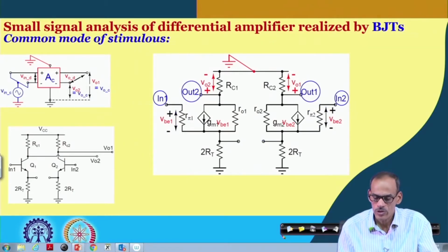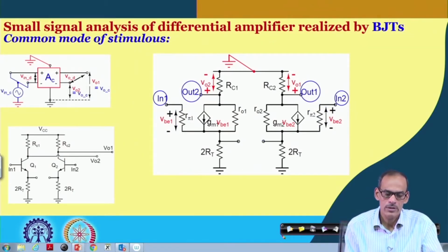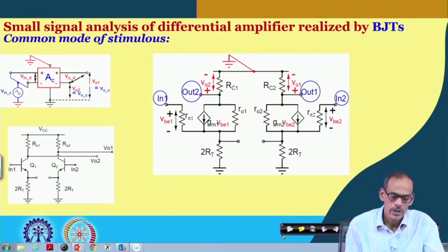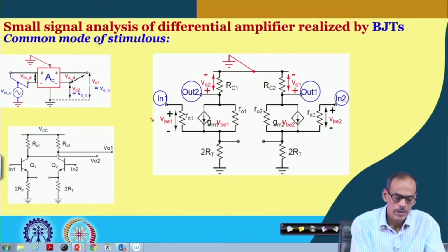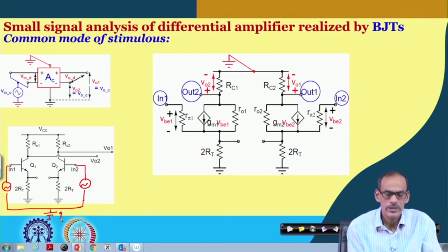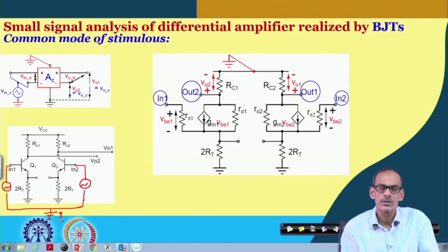Now, so far we are talking about the small signal situation. Now, you may recall that while we are applying the signal at the input, definitely we are also applying a meaningful DC. So, now next question is what may be the meaningful DC, that can be analyzed by considering large signal behavior of this entire circuit.